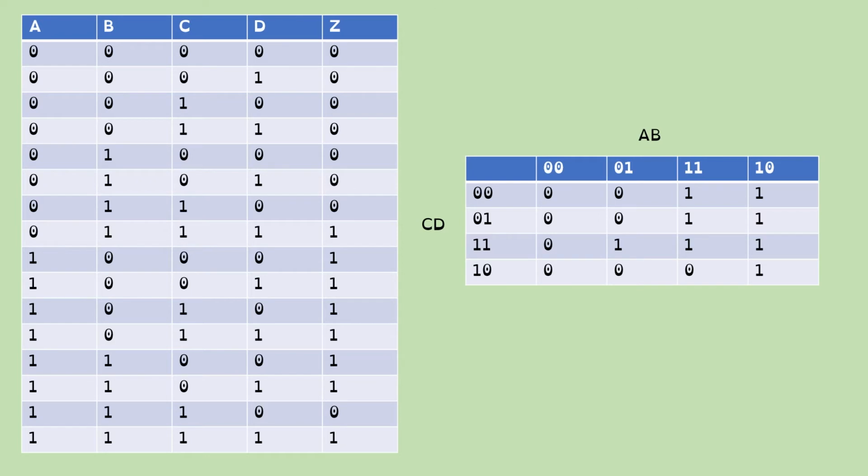Let's also do the bottom right. So the bottom right in the K map, we're going backwards from here, 1, 0 is the right hand end for AB, and 1, 0 for CD is the bottom. So the ABCD is 1, 0, 1, 0. And if we look in the truth table at 1, 0, 1, 0, scanning down over the 10th row, our Z value is 1. So that's the value that we put in the K map.